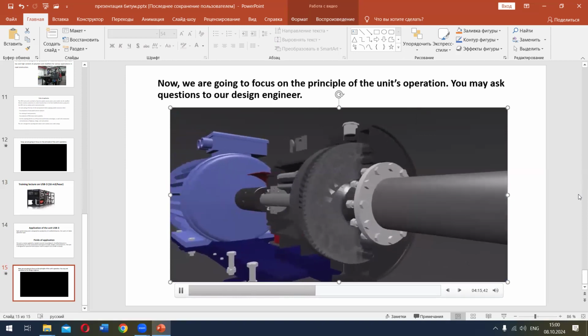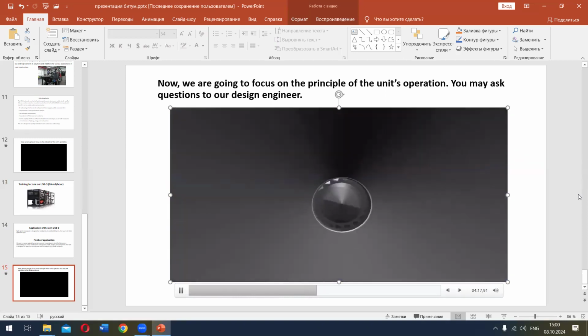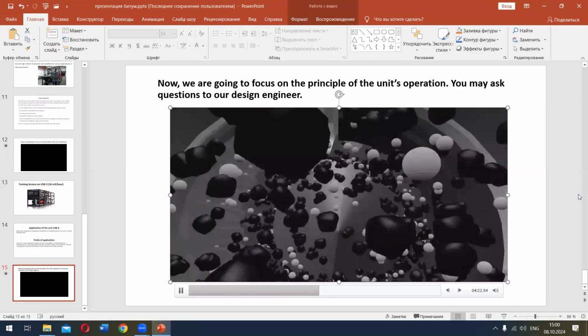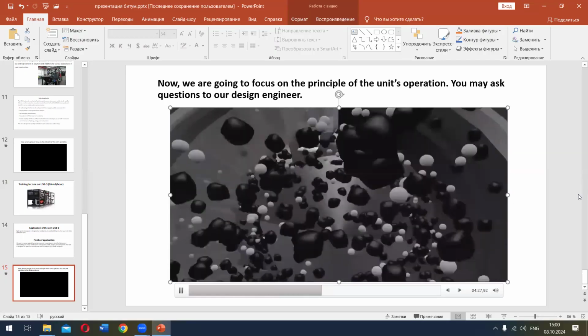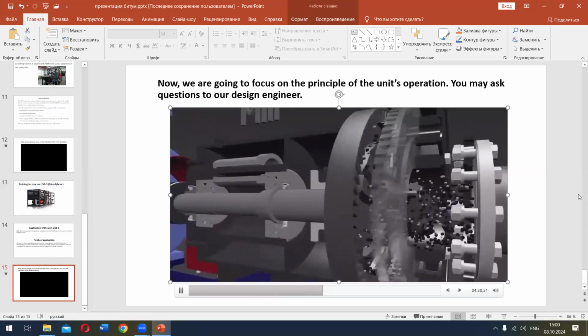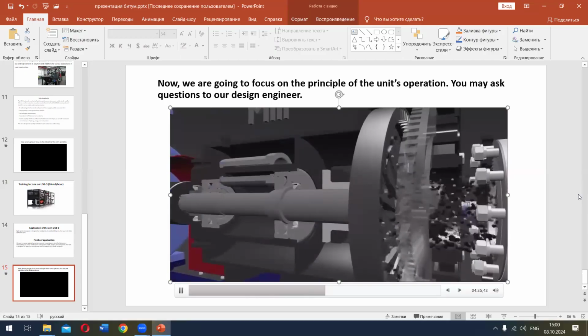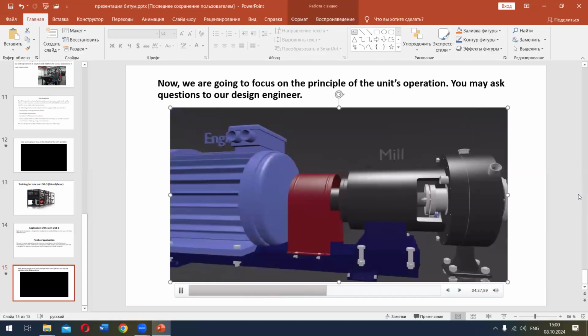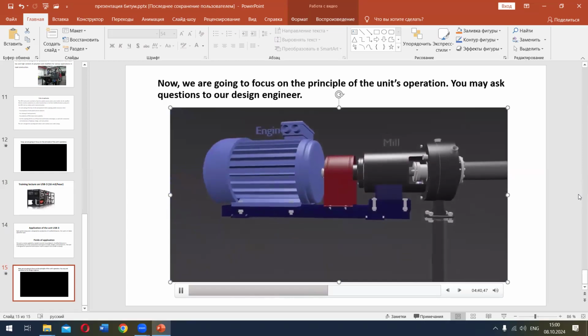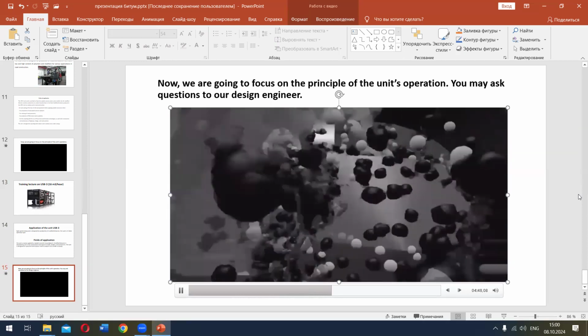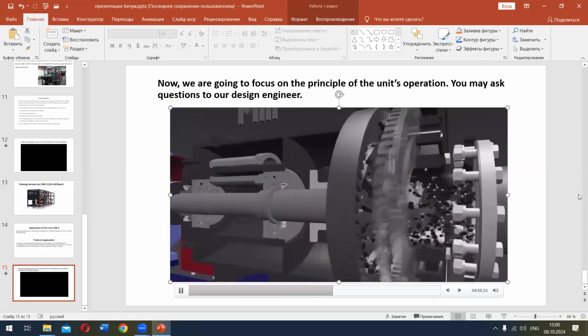Next, the mixture is supplied from the primary mixer to the primary mill where grinding and mixing occurs at a higher level. Having passed the primary mill, the mixture of bitumen, polymer, and plasticizer enters the secondary hydrodynamic mixer wherein pure bitumen is supplied to the nozzle by a bitumen pump, and the primary mill mixture and the adhesion additive are fed into the vacuum chamber. After passing the secondary mill, the mixture is fed into the storage tank through the modified bitumen supply pipeline by means of a three-way valve.